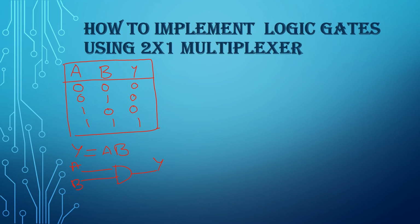Now let's draw the hardware circuit of a 2x1 multiplexer. A 2x1 multiplexer has two inputs, one selection input, and one single output. Here the output is Y, the inputs are I0 and I1, and the selection input is S. From this, the logical expression of a 2x1 multiplexer is Y is equal to S bar into I0 plus S into I1. This is the logical expression of a 2x1 multiplexer.